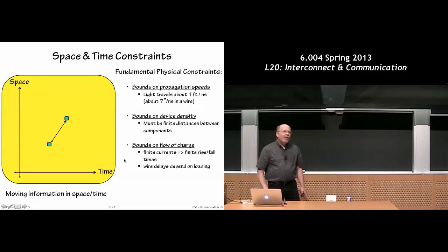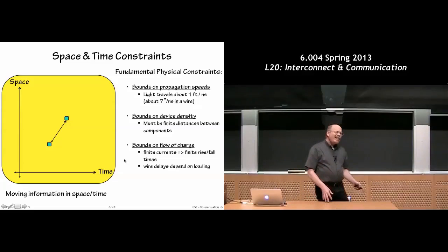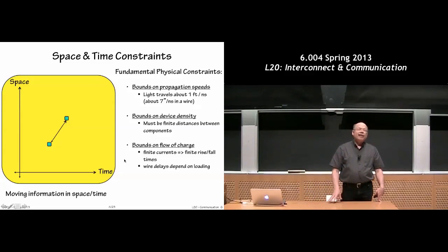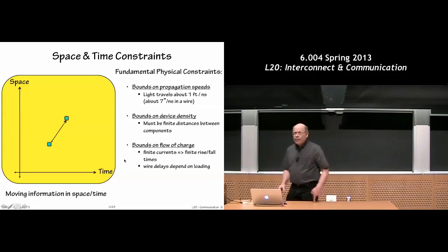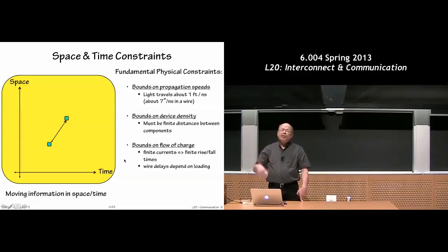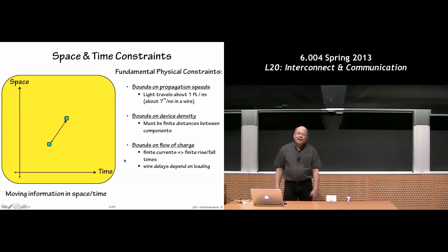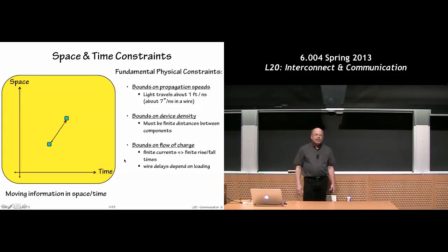And finally, you could say, well, what makes things slow anyway, or fast anyway? And the answer is, well, we're charging and discharging these nodes. We're using these voltage-based representations of information. And simply charging and discharging capacitances through these switches takes time. And the way information gets propagated along wires takes time.